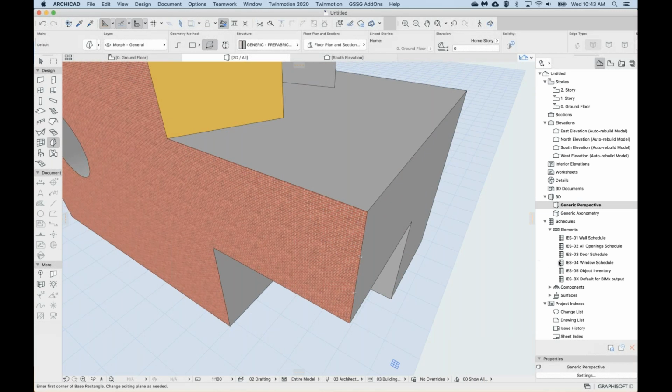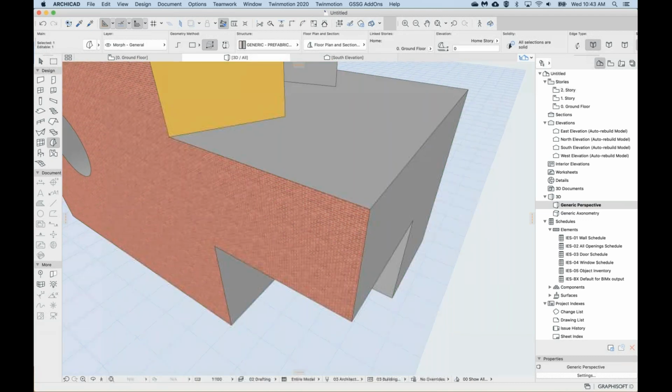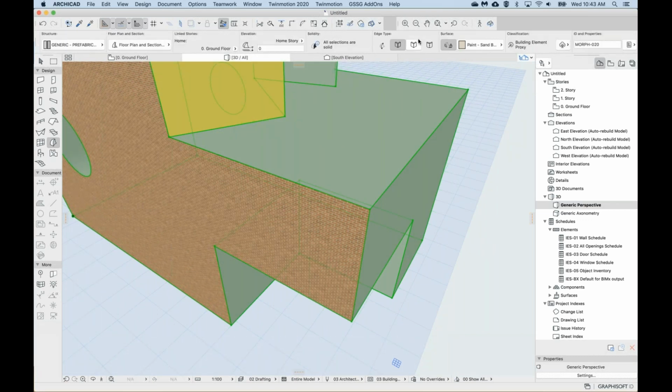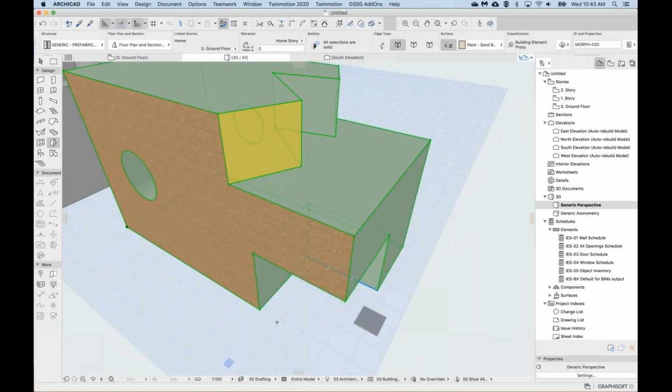Great. Not solid. Just check when you select. So sometimes when you start editing, it may break depending on if it's not so accurate. So just make sure that the selections are solid. So this Boolean operation, I don't think works if they're not two solids. So if they're just surfaces, then the Boolean operation won't work.